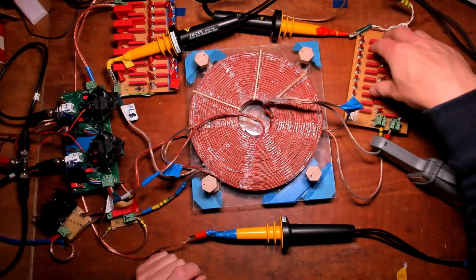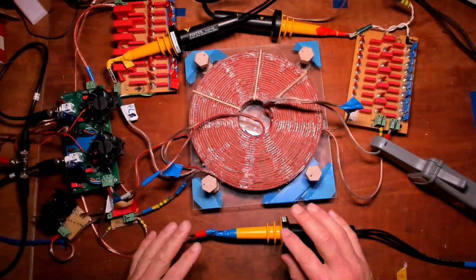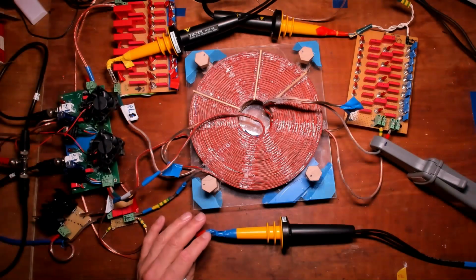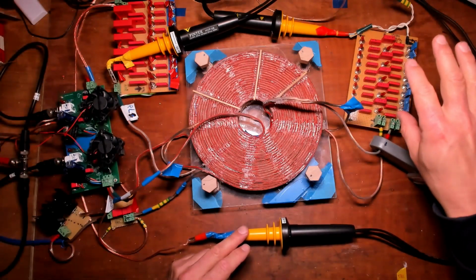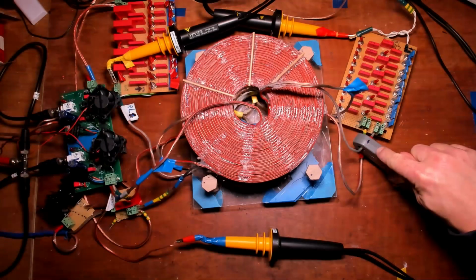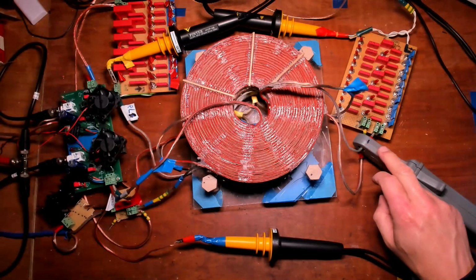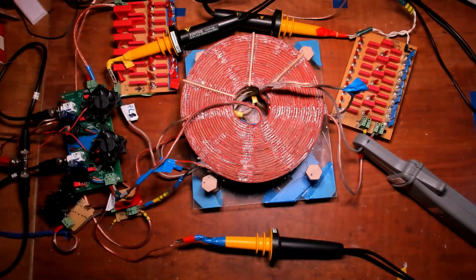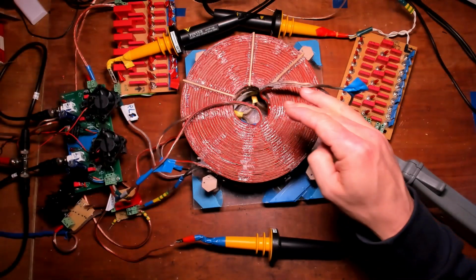The voltage probe of L3 and the voltage probe of L1 will be swapped because I only have 4 channels on my scope. There will be only one connected at a time, and I will tell you which one it is. One more thing, the current probe has an arrow on it, and this arrow is pointing inwards to the inside rim of the L3 coil.